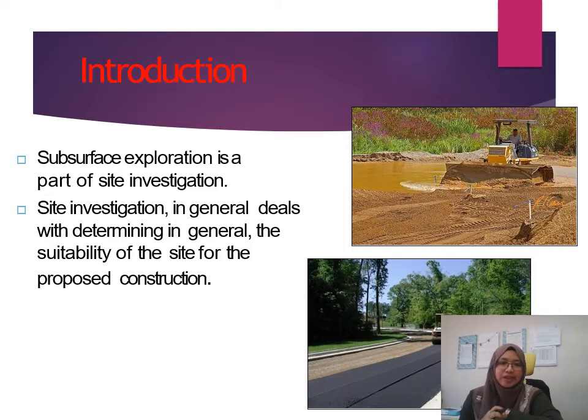Okay, for the introduction, subsurface exploration is a part of site investigation. We want to explore what type of soil there is and what the properties of the subsurface soil are. Subsurface means underground, below your ground surface. So we want to explore your site. It is also called site investigation. Site investigation means you investigate: you gather all of the information about your site, and then you analyze it, and from that you can propose the best construction method for your project.